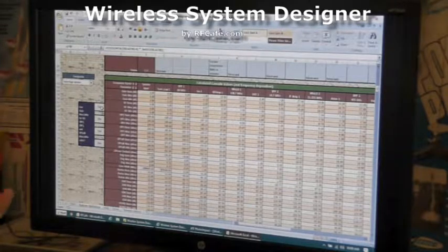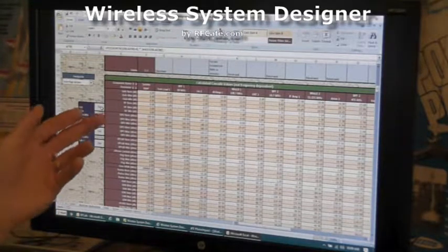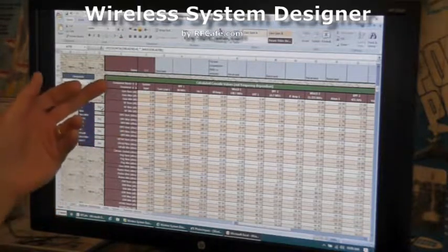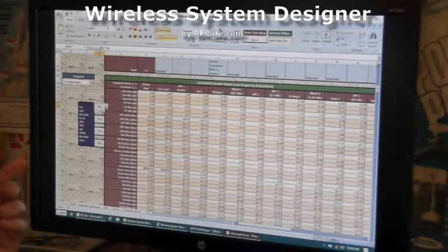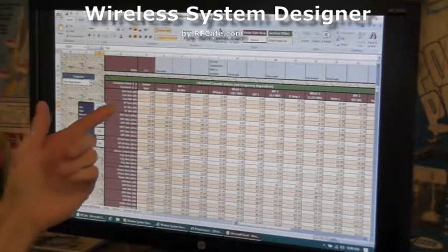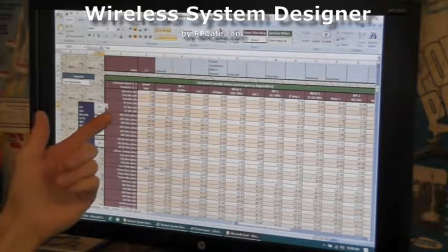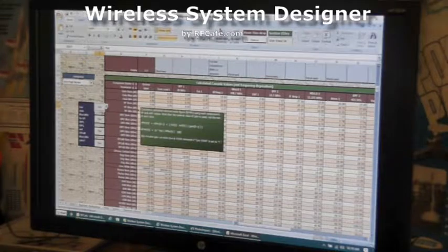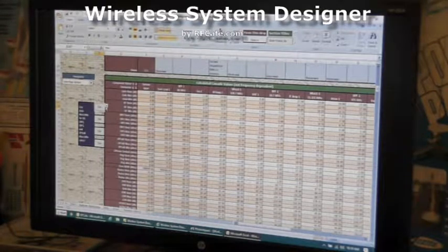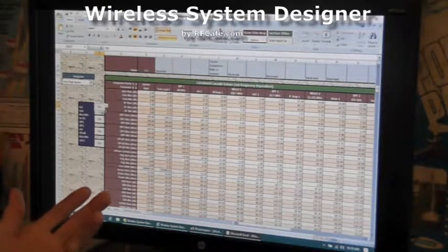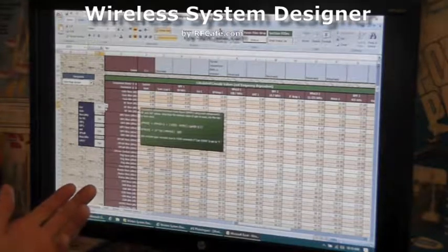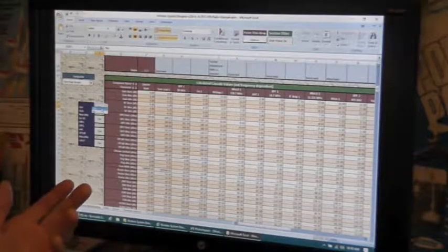So you're looking at just the variation of these parameters with the nominal gain to see how everything changes. You can either include the gain min-max values in the min-max values of noise figure, IP2, IP3, and or P1dB, or you can not include it in there. So you're looking at, with nominal gain, what is the variation due to just that particular parameter itself.